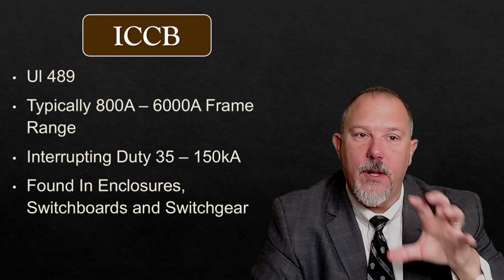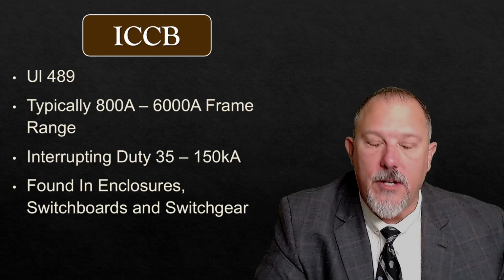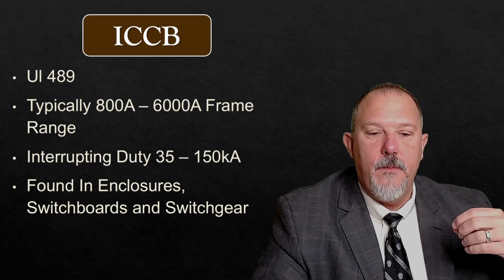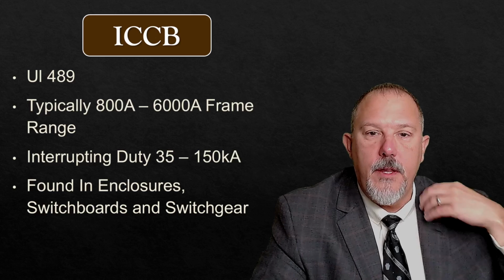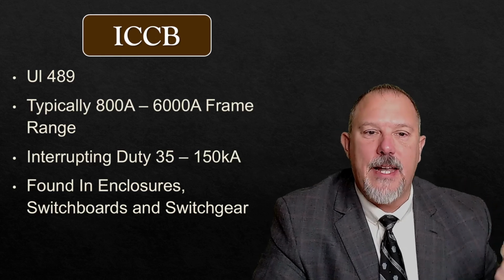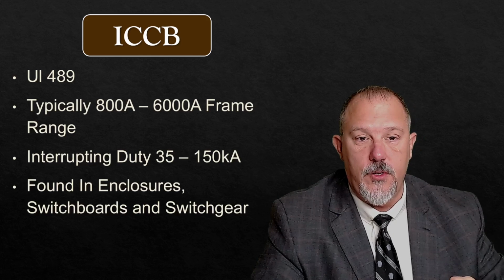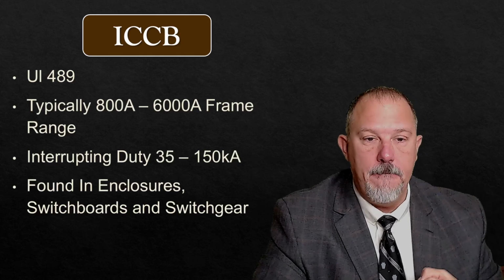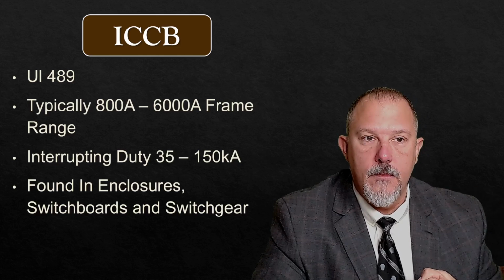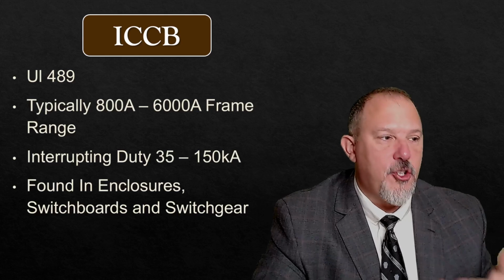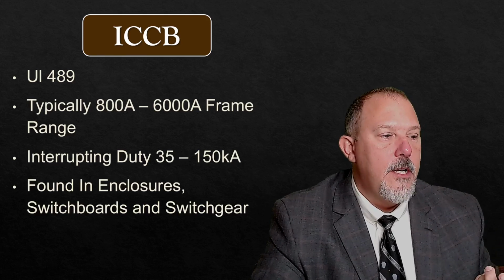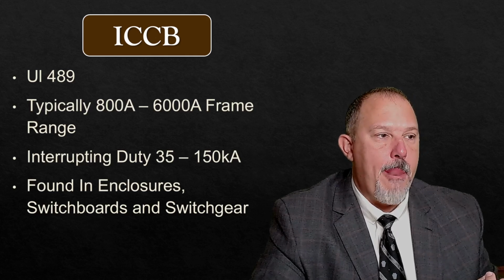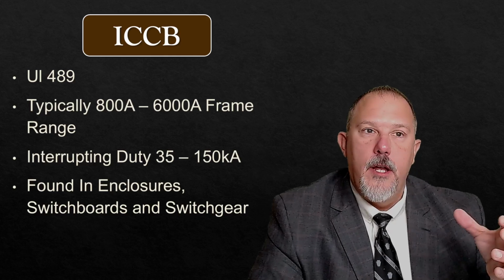In any case, I'll just talk while I'm looking. The insulated case circuit breaker and the power circuit breaker, for all that matters, the fundamental principle is I want to keep my contacts closed during these higher fault currents. That helps me make sure that all of the power distribution system components downstream do their job.